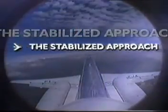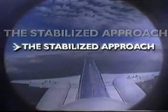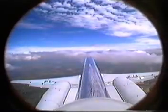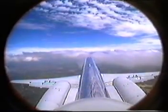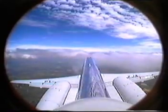The final solution is thrust, but it may take a lot of time, so this option is practicable only at a safe altitude. To keep away from the potential development of high sink rates, fly the stabilized approach concept. The stabilized approach. When the whole approach is properly controlled, the possibility of something going wrong is drastically minimized.